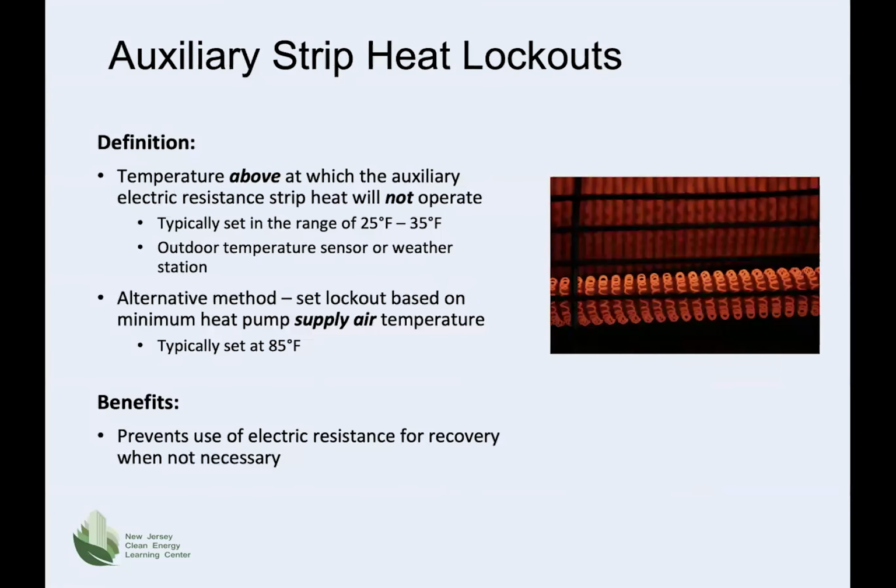Auxiliary strip heating. Now, this particular strip heating they're talking about here is pictured, and it's sometimes packaged inside the heat pump itself. This is not an electric baseboard heating or something outside the scope of the heat pump. Now, this is installed as an integral part of the packaged heat pump. The purpose of the lockout is to make sure that the heater's not activated when it's not needed to meet the heating load. The lockout can be triggered in one of 2 ways.